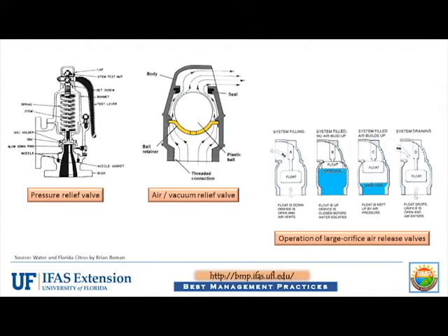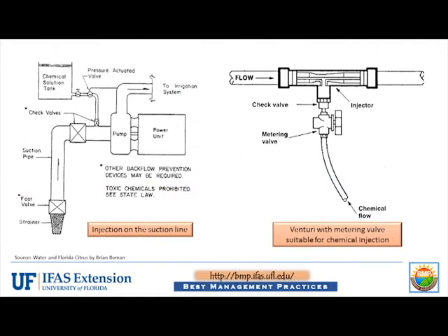The vacuum breaker will allow air to enter the pipe when pumping has stopped so that water flowing back to the pump will not create a suction, drawing additional water and chemical from the irrigation system to it. The vacuum breaker must be located upright and above the irrigation pipe so that it functions effectively. Chemical check valves. A functioning check valve on the chemical injection line is also required.